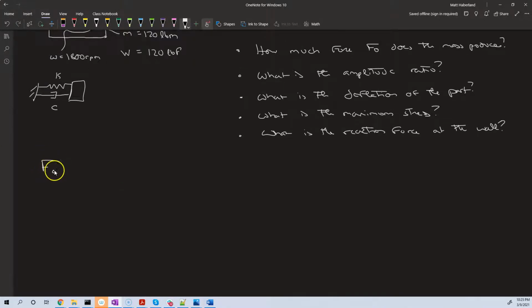So we've got a mass that is rotating at a distance r, and the force is m r omega squared. You've probably learned this in physics before, so we're not going to derive that this time. Right, we've got the centripetal acceleration, you might remember, is r omega squared. Maybe you've seen it written as v squared over r. Well, v is equal to omega r. So if you plug that in, we've got omega squared and r squared on top divided by r. You end up with an r times omega squared, right? And so that acceleration times that mass is equal to F naught. Let's figure out what that is.